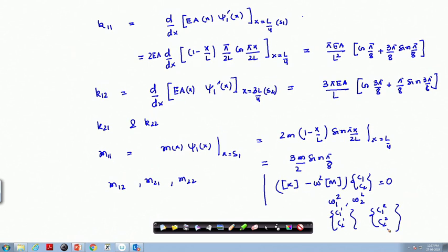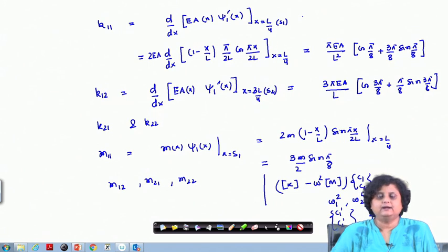The best part of the collocation method is that it does not involve any integration, unlike the Rayleigh-Ritz method. So, the calculations are much simpler, and we can even use a larger number of trial functions and get a better approximate solution for the mode shape and natural frequency.